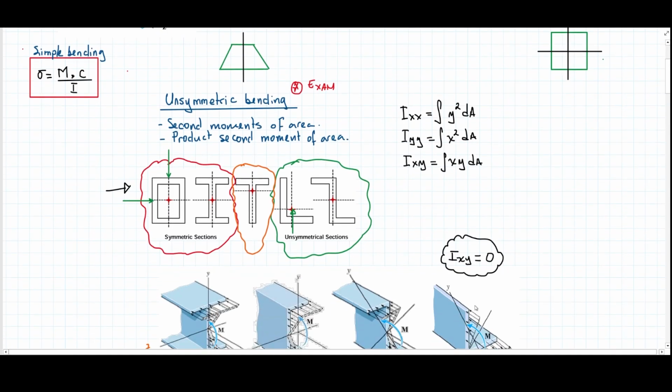Yeah. And that's something that is nice, but when you don't have symmetrical sections, then those typically given reference axes are not aligned with the principal axis. And the reason for that is that commercially, or structurally, when we go in practice, these are the typical axes. For example, this one here and this one here are the typical axes that you use for L-shaped beams or Z-shaped beams. These are the ones that you use for construction purposes to align your stuff. But those are not your principal axes or principal axis of symmetry.